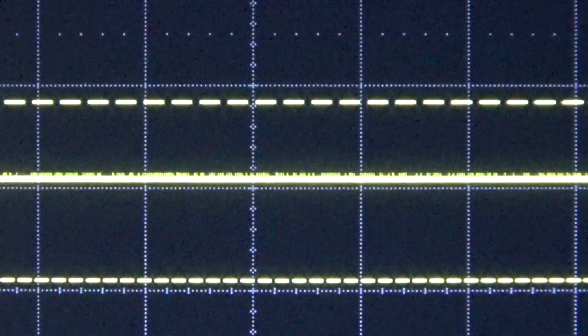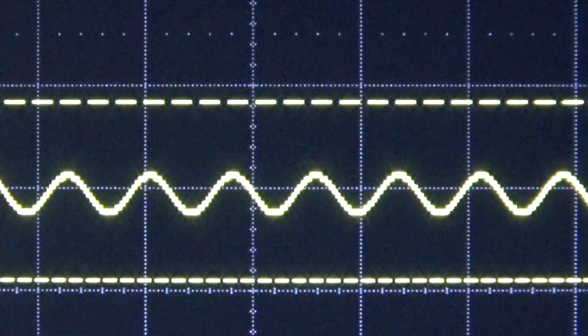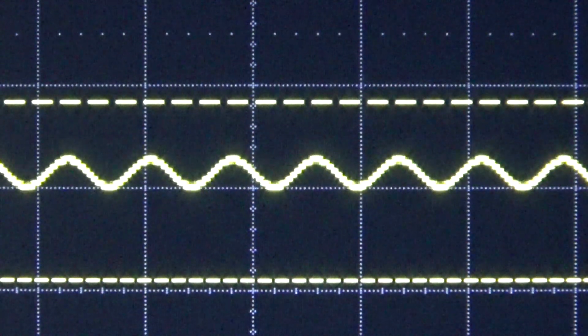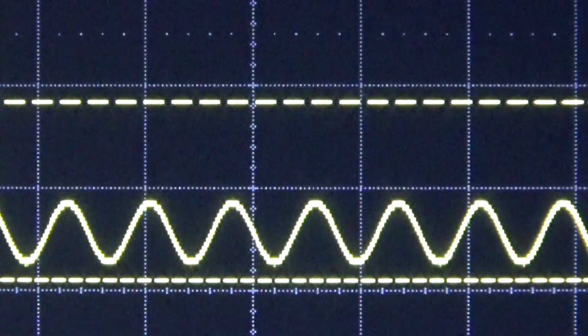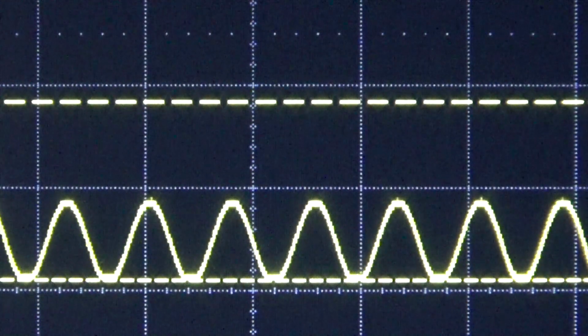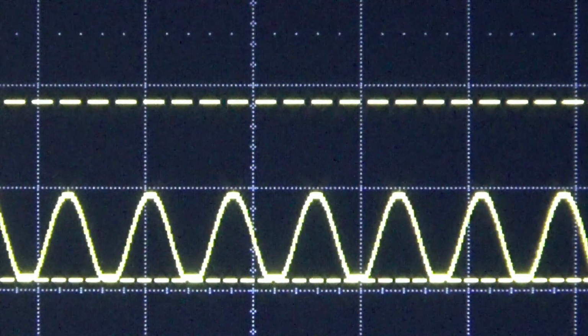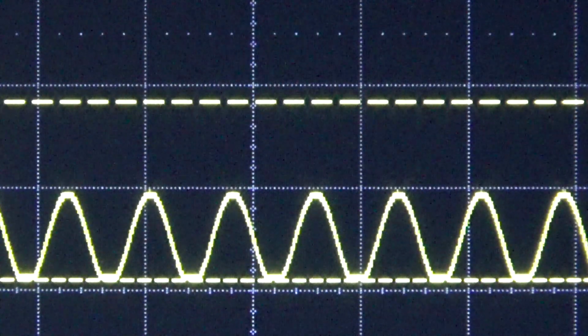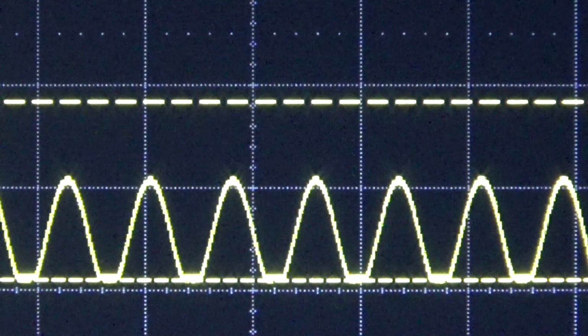Here we're viewing the output DC offset on the oscilloscope. The cursors indicate the minimum and maximum output swing. As the DC offset lowers and it's too small, we can see that the output becomes clipped. This is where it's nonlinear.